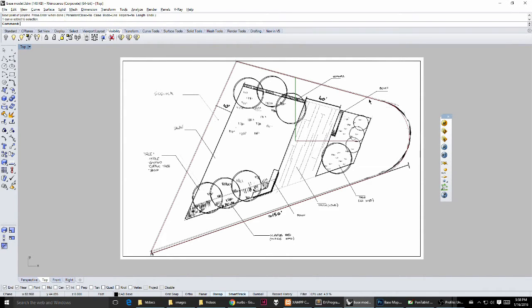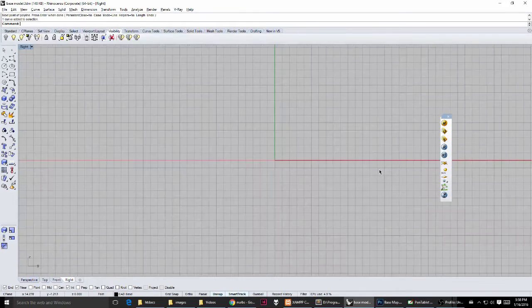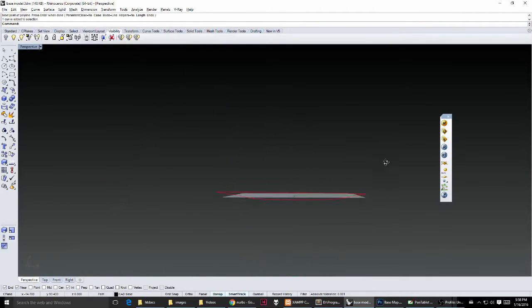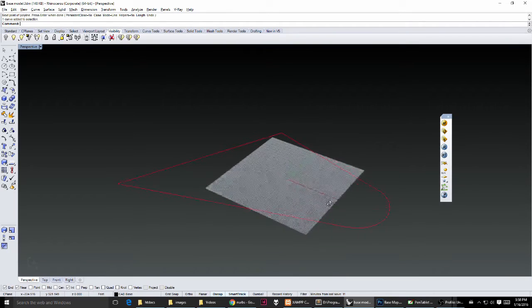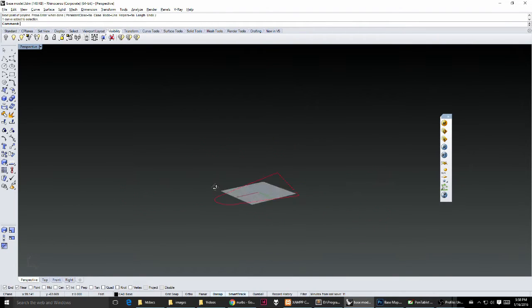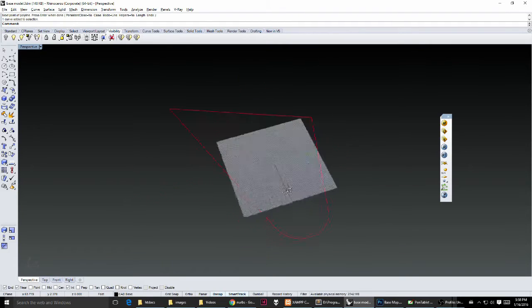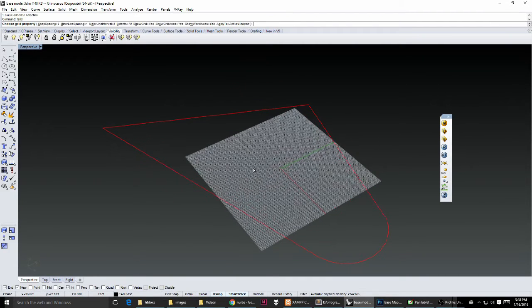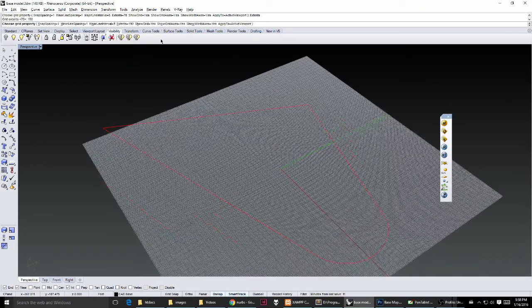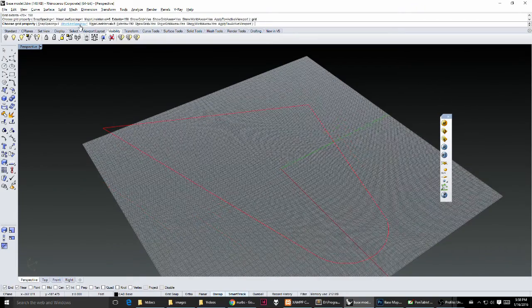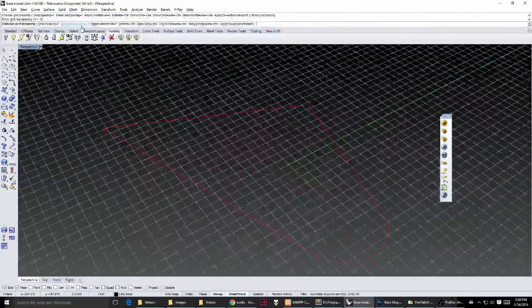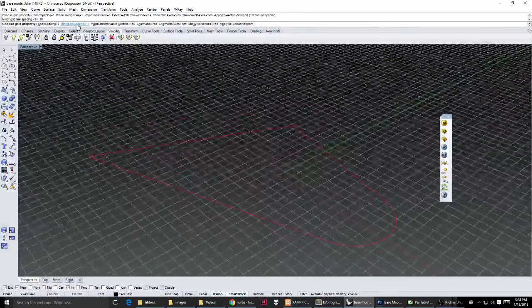In this case, it's a polyline, and I'm switching between arc mode and line mode. And I'm working mostly in 2D at this stage. So I'm just tracing over the existing sketch. Here is the trace in 3D. It's a closed loop, so everything we're going to make is watertight. The reason for that is because we're going to extrude all these elements in the next stage.